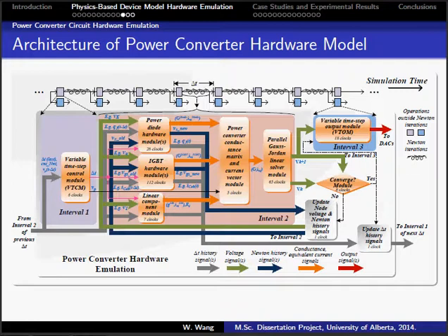In interval 1, the current time step is decided by the Newton iteration times of the last time step calculation. Also, the PWM switching signals are calculated too. Interval 3 is used to generate the output values, which are in turn sent to DAC.